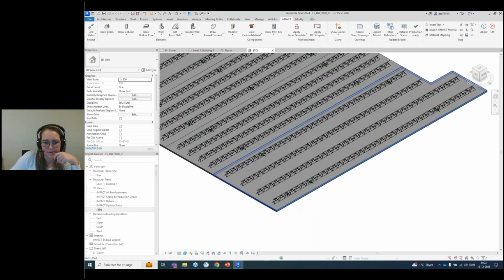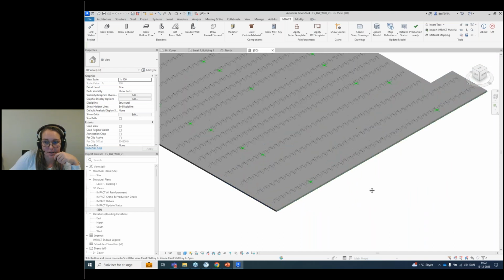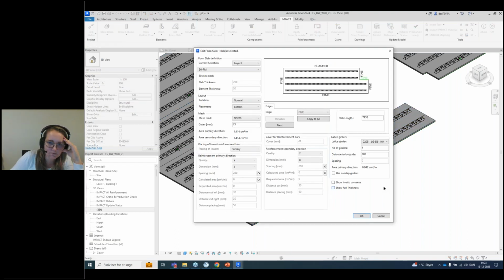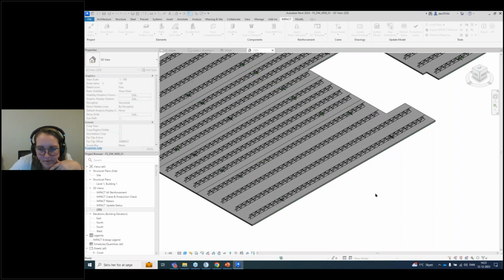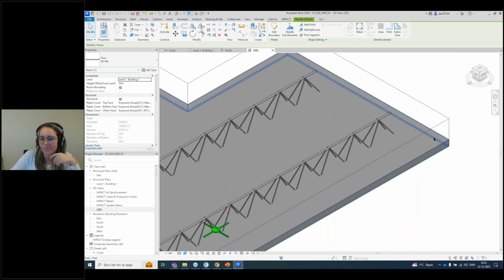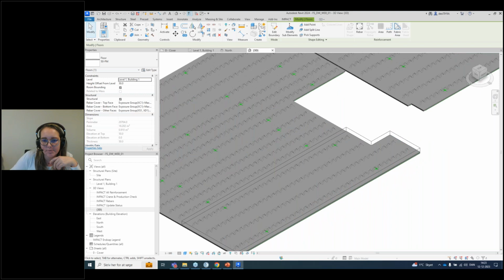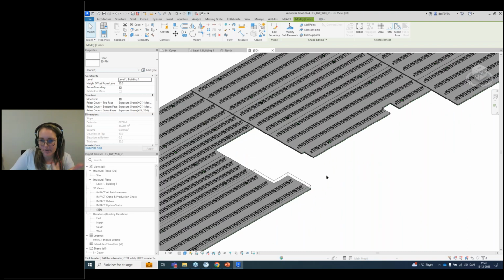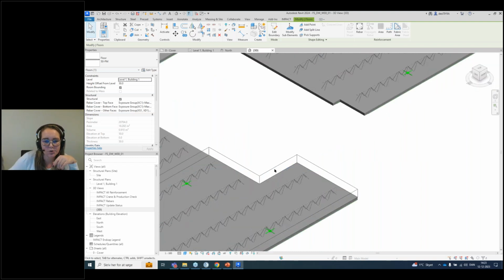What we see is the concrete plate and the girders. If you go to the Edit Formslab again and select a Formslab, then you can see that we have 2 options here. If you go to show full thickness, you can see here it shows a frame around the slab, which refers to the full thickness of the slab. And this is especially useful if we're going to do some detailing, like in a while, and we want to see where the top of the element is. So this is just a frame around.